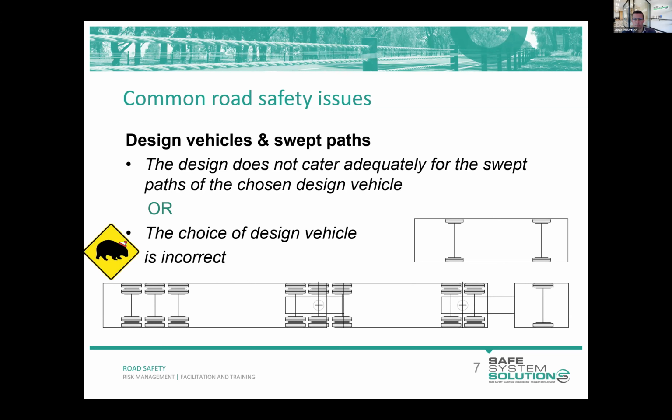So make its turns and all movements from within the correct lane to not encroach curbed areas or islands, not have to swing onto the opposing traffic lane to make a turn, these type of things. We also talk about checking vehicles, and any design will have a nominated design vehicle or vehicles and a checking vehicle.